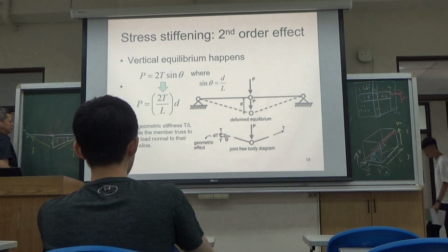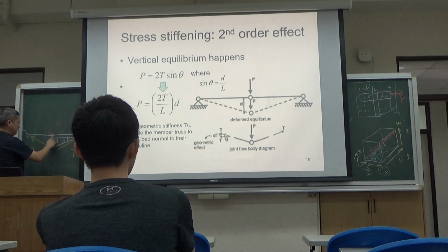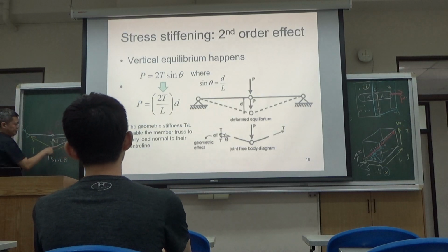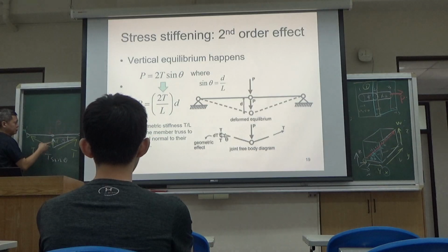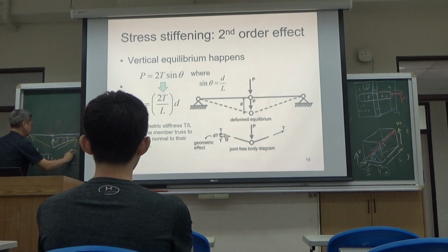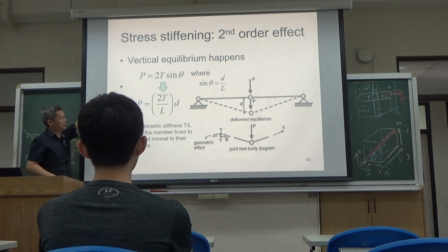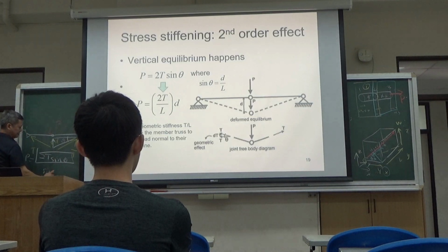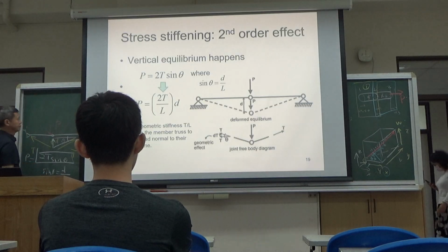If you draw this, if this hypotenuse is the tension, the vertical part is T sine theta. You see that? Tension along the rod is resolved into a vertical component and a horizontal component, and the vertical component is going to oppose the P. And you can also find what sine theta is. This is the distance divided by the length.